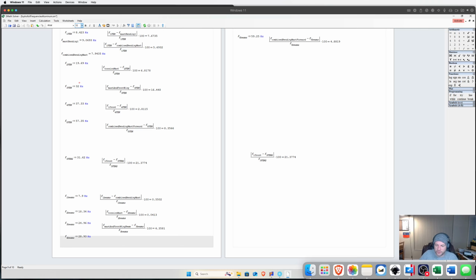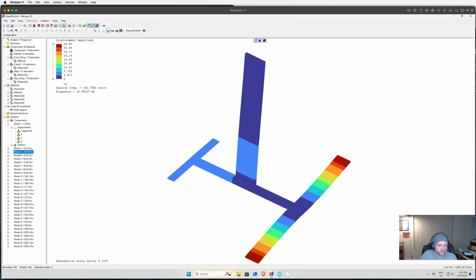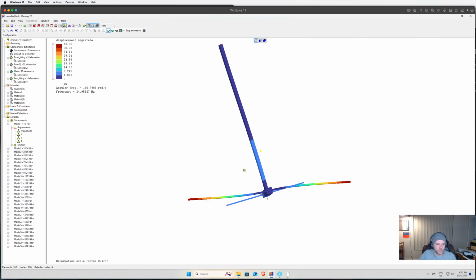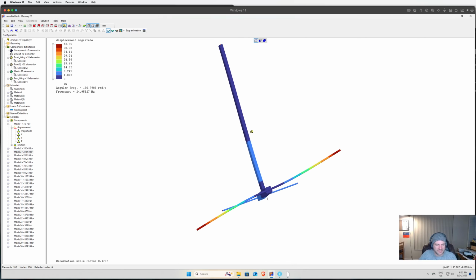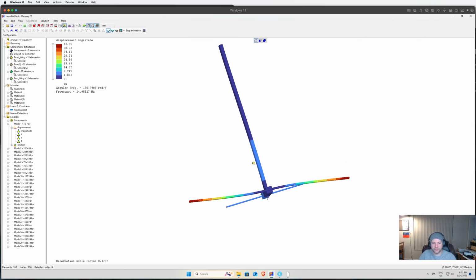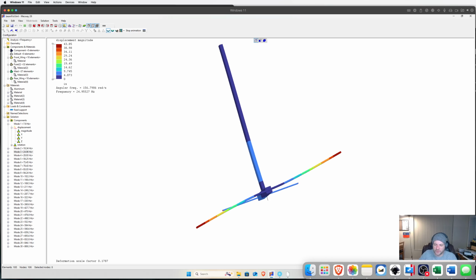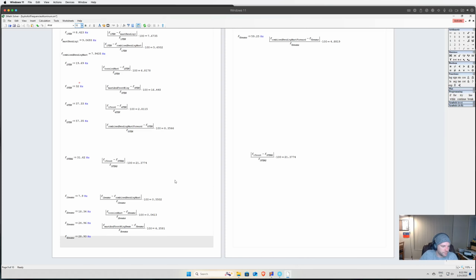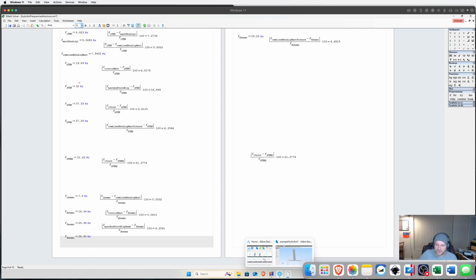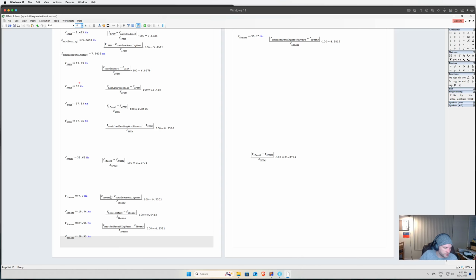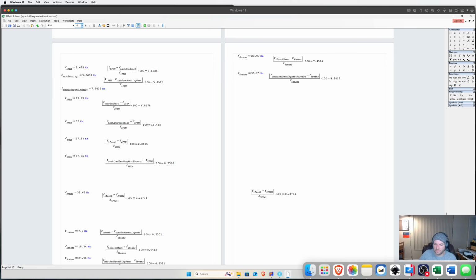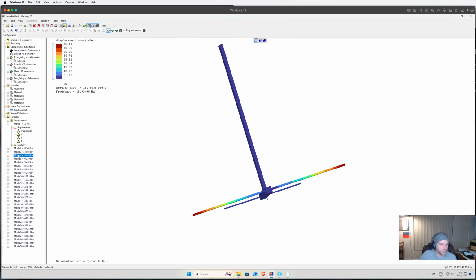And third mode, I'm just going to go through all these first 5 modes, was also this combined twisting of the mast, bending from torsion of the fuselage and the mast combined with the flapping of the wings, which drops it from the pure flapping mode of the wings. So I got 24.96. Was that right? 24.96. Just making sure my number's right. So I got within 5% of that. That's good. We get a little bit more divergence when we start getting higher modes because it's harder to understand all the different effects.